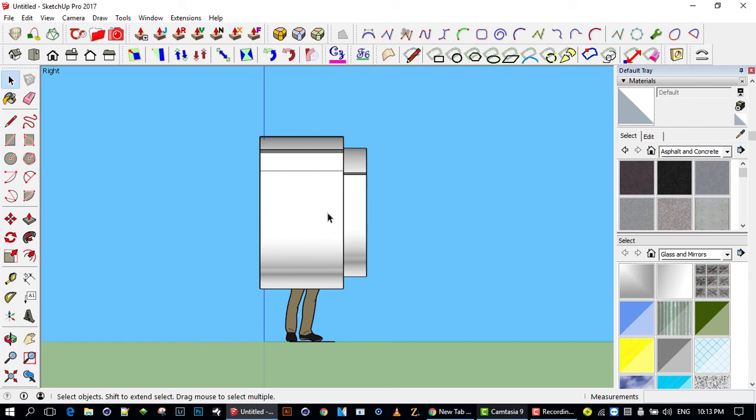The G is for making a group. The S is for sizing, and my S is defaulting to the FredoScale for resizing. The Z is to zoom into a selection. The B is for bucket tool or the paint bucket tool, and mine defaults to Through Paint, which is one of the Fredo tools. And the M is the move, which creates an extra copy with a plus sign.